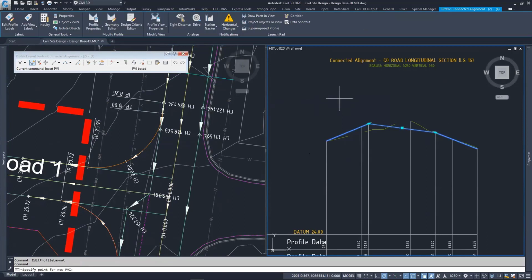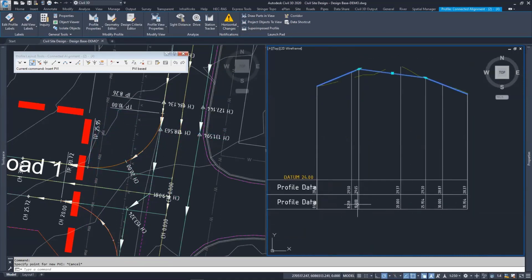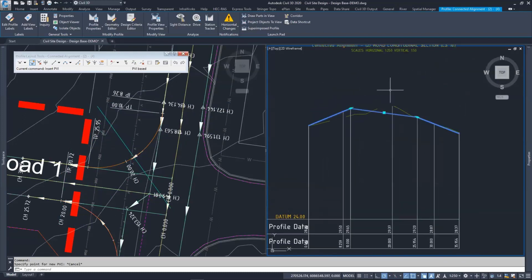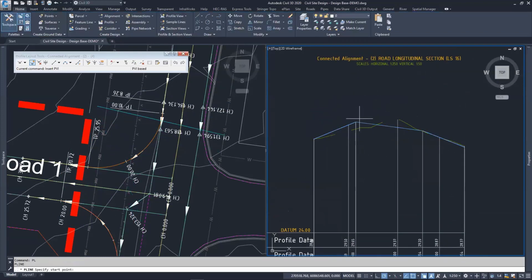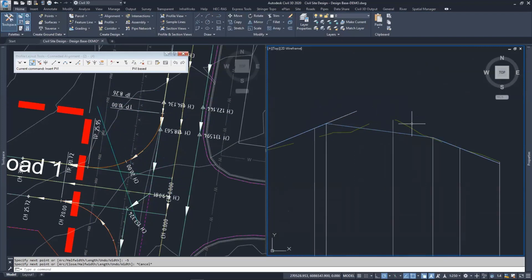Now, because we've got incoming and outgoing data, you can adjust this sampling of the road coming in, and this portion in here, you can apply edits in between these two here. You can see here on my changes where I changed the sampling to 10 meters, so 0 to 10, it sampled that off the incoming alignment. And from this one, it's 25 through to 35, so 10 meters on both sides. Because I'm in AutoCAD, I can draft locations in.